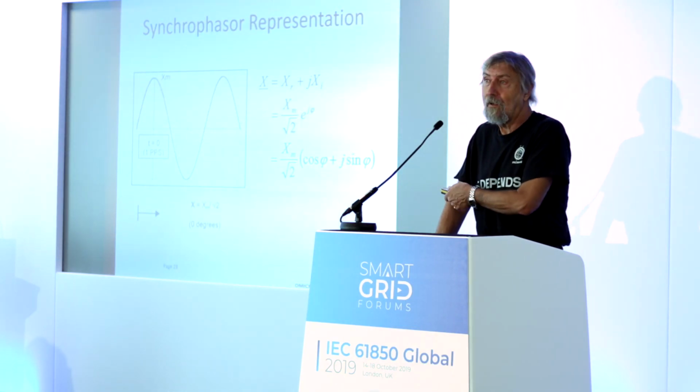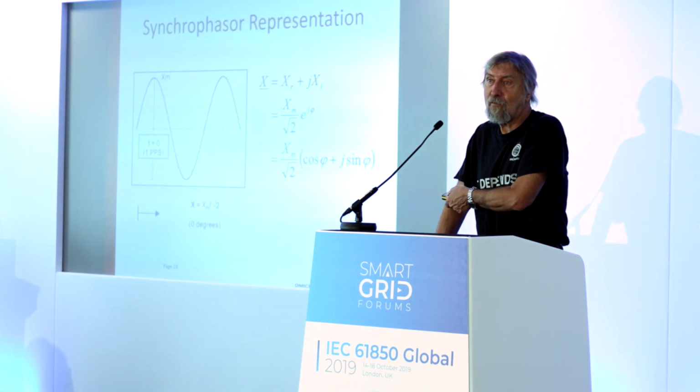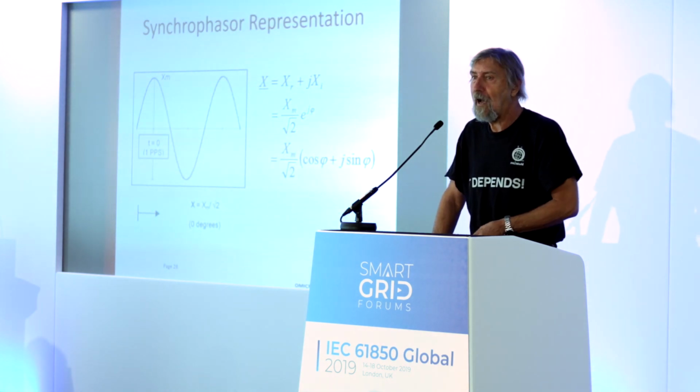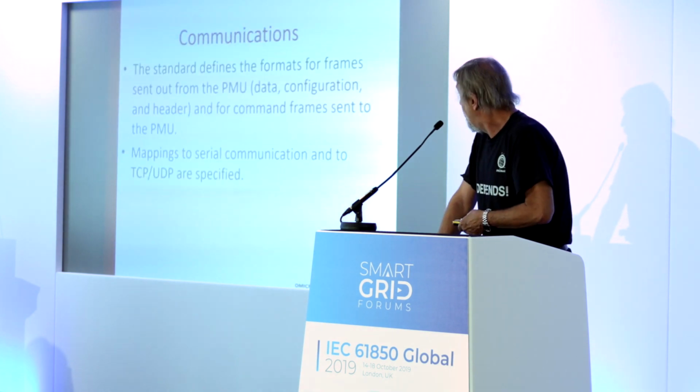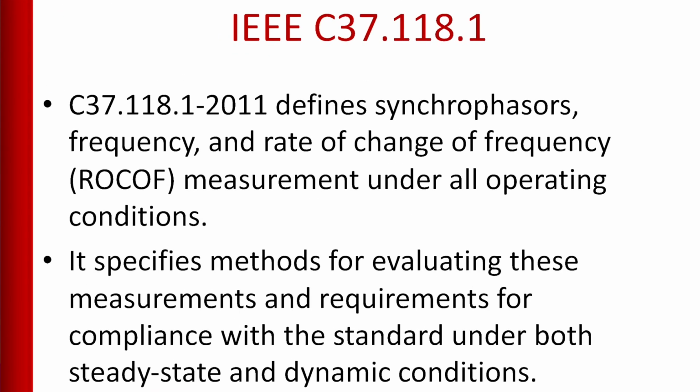Why did they pick the top of the positive waveform? Don't ask me. Ask Arun Phadke and Mark Adamiak, okay? So anyway, it also defines communications and the date format. This was replaced later with the 118 edition 2 standard, if I can say, that was split in 2 parts. Part 1 defines the measurement of the synchrophasors, and part 2 defines the communications.